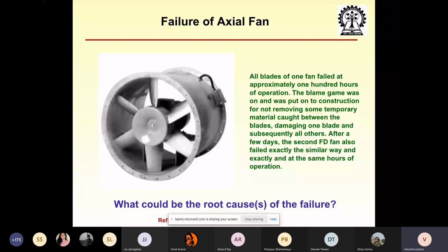Whatever your driving frequency is, over here as the blade rotates there will be some vortices created, which are going to vibrate the blades, and the frequency of this external forcing will depend on the rpm of the blade. Now in this particular case, at the speed at which they were operating, there was a resonance in the system.